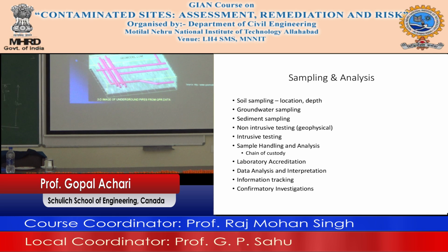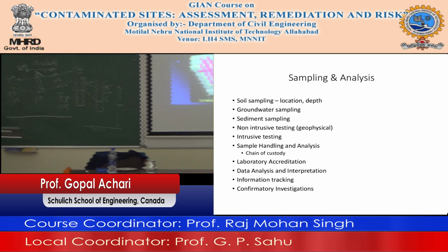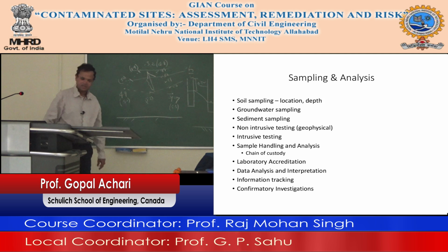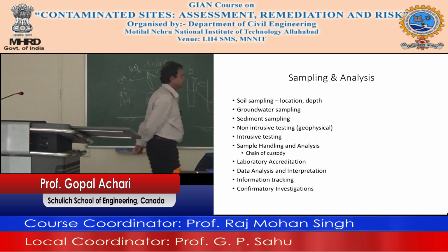Non-intrusive testing: we talked about GPR, EM, ERT, seismic methods. The intent is to find tanks, objects, salt, underground contamination plumes, and so on, like something you see here. Intrusive testing is where you actually drill a hole. Manual samplers are used for superficial soils and mechanical core samplers for soil at depth, with vertical and horizontal delineation, sampling, handling and analysis, and chain of custody. The other thing is the accreditation of the labs.